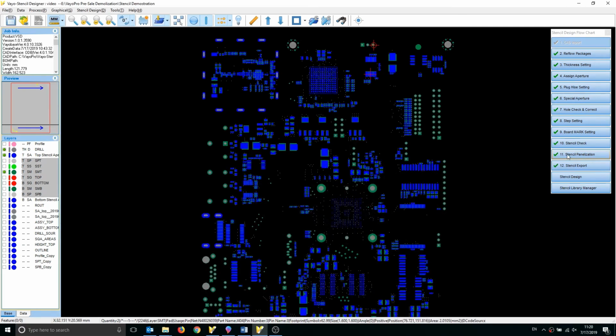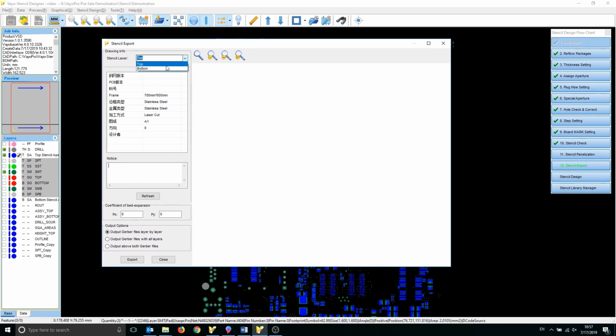If there is no panel for the training job, we could jump to the final step of stencil export. If you need to generate panel for stencil, please refer to a separate training video. That's great, we've accomplished the stencil design for this PCBA. We can export the design to the Gerber files.